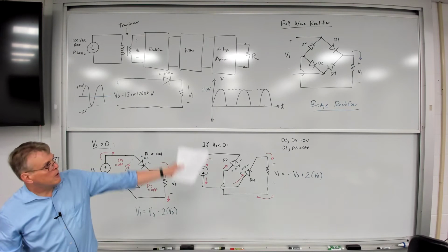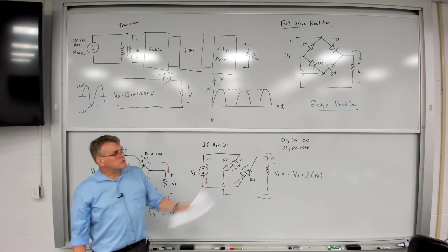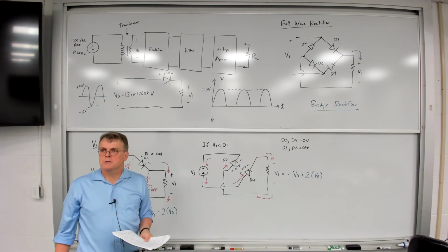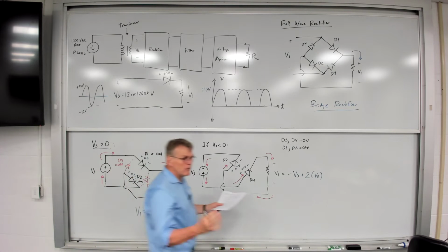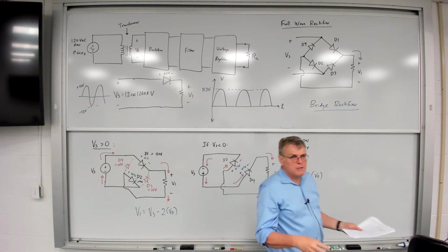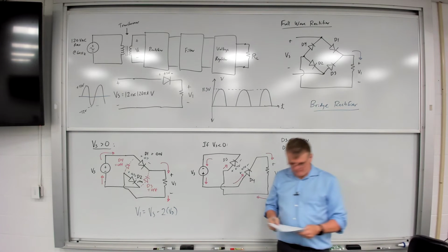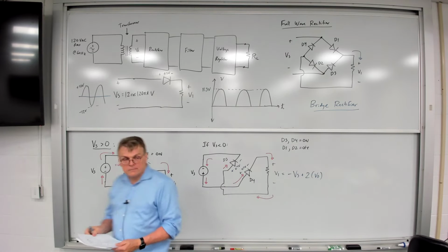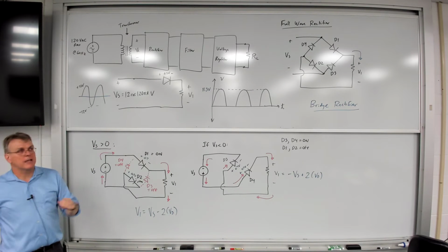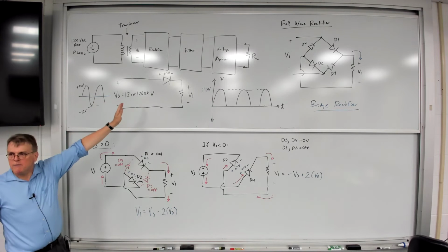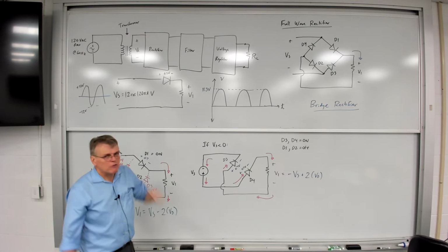And in terms of component costs, all you need is 3 extra diodes. So this is really a very popular technique, and you will see it used all over the place even today. If you look in the book, it goes over some other ways of doing full-wave rectification. I'm not going to spend time on them, but you can look at those yourself. Okay? So this is the first step in my power supply design. I've gone through rectification, and now I've got an output voltage coming out of the rectifier.